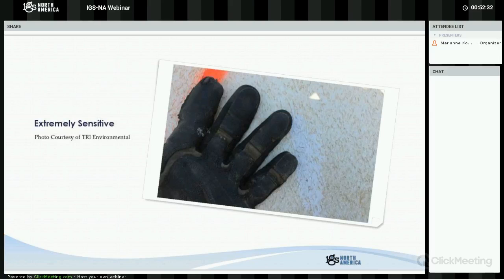So I'm just going to read a sentence from the most recent revisions of the spark testing method. It says, "Electrical leak location methods, in addition to the spark testing method, may be used on electrically isolated conductive back geomembrane installations." So the only reason I'm mentioning this now is that the conductive back geomembrane product has always been so intimately linked with the spark testing method that it's really hard to separate the two.